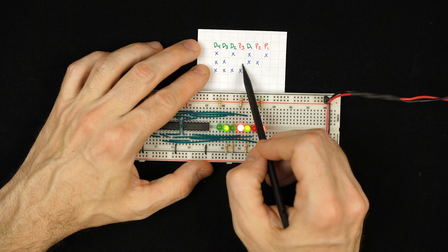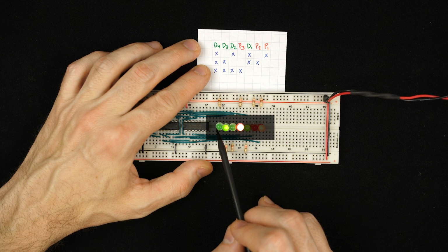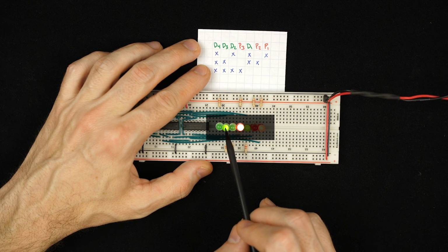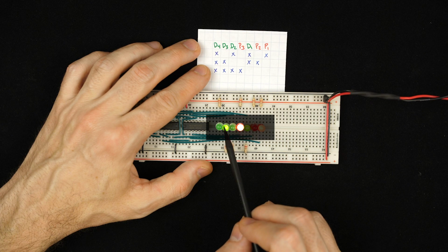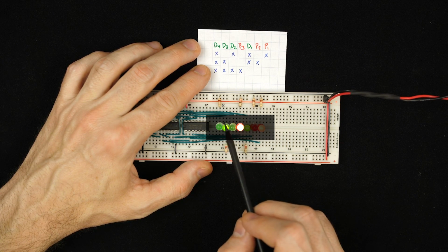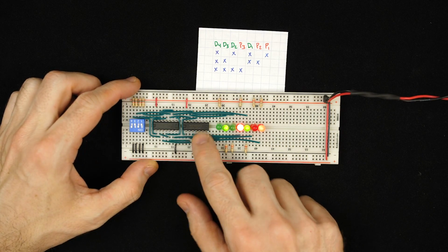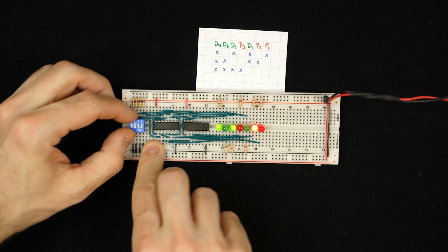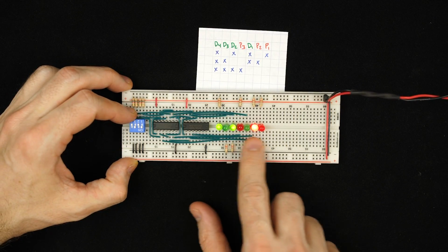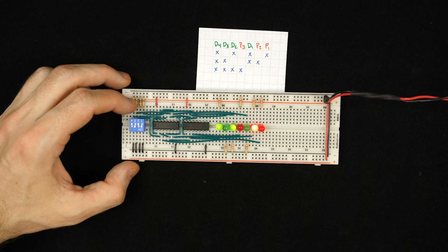And then parity bit 3 covers just these last 4 over here on the left. And so we have 0, 1, 0. And so because we have 1 LED on there, we need to turn on this second one in order to ensure that there's an even number of 1s within that group. And because of the way we've wired up these XOR gates, as we switch these on and off and adjust our inputs, the output's going to change automatically to ensure that this is always true.